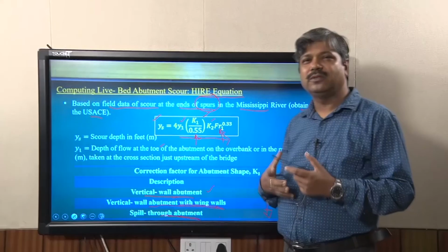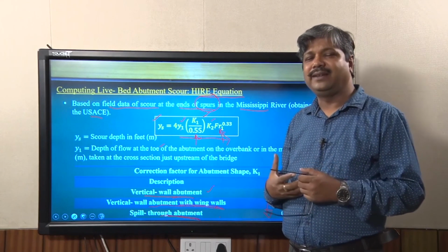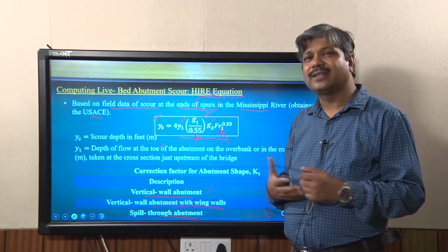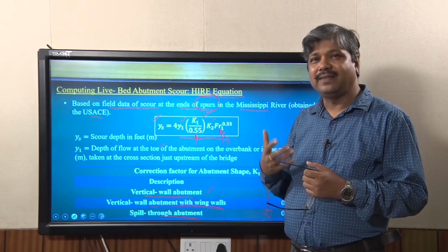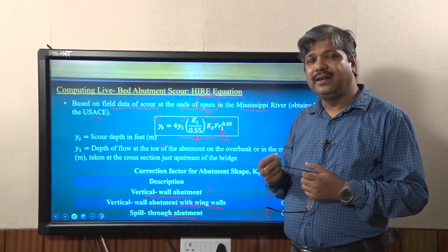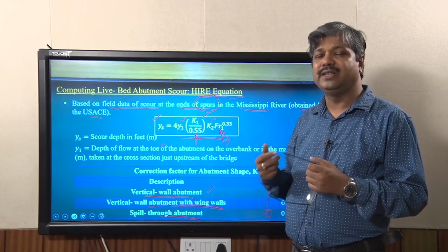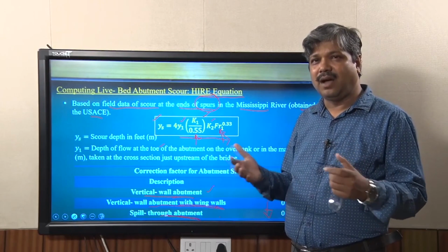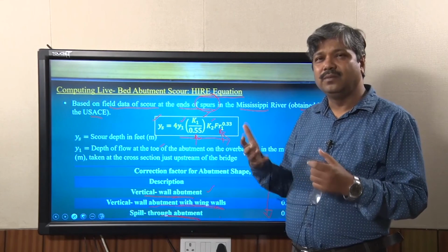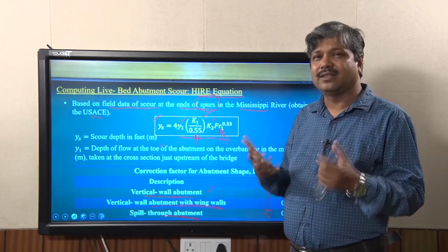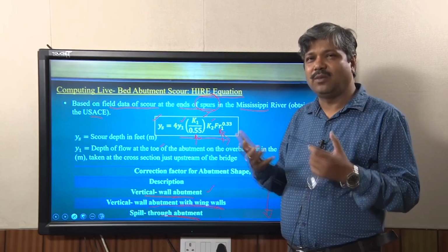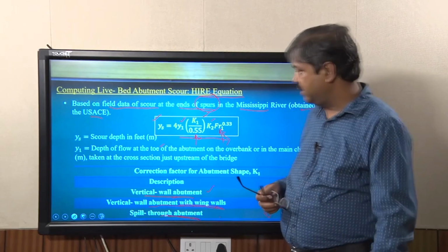My point is that when you look at the scour equations, that is knowledge for us, and it gives a hint on how we should design an abutment with minimum scour. We try to keep the scour depth minimum, otherwise the foundation cost is going to increase.